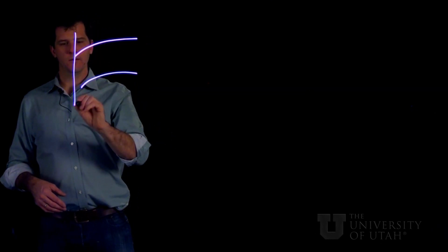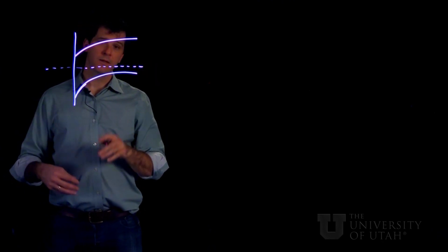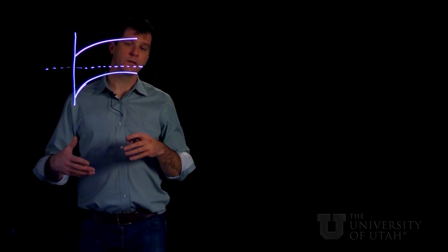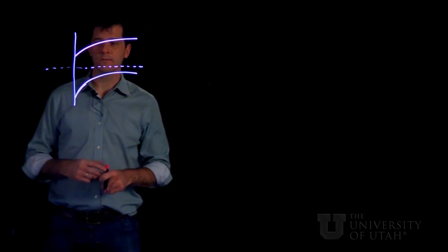Okay, so the first effect we're going to consider is called subthreshold conduction. We've talked about the channel as being in either an on or an off state, sort of implicitly in our discussions so far. But what we have to realize is that we're dealing with a semiconductor here, which no matter what voltages or band bendings we apply to it, is always going to have some amount of conductivity in the channel. And this showed up also in our last discussion where we had the parasitic resistance through the channel as one of our equivalent circuit elements.